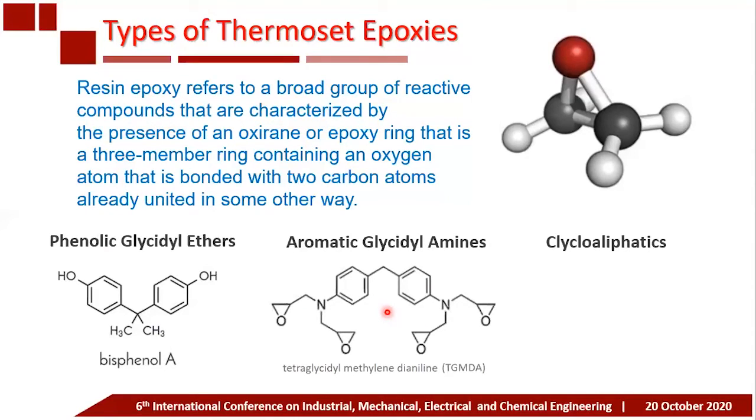This epoxy is formed by the reaction of epichlorohydrin with an amine, with aromatic amines stable in high temperature applications. This epoxy, TGMDA, has excellent mechanical properties and high glass transition temperatures, and is stable for advanced composites for aerospace applications.